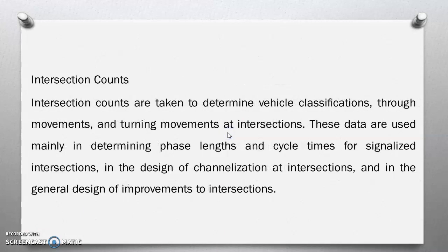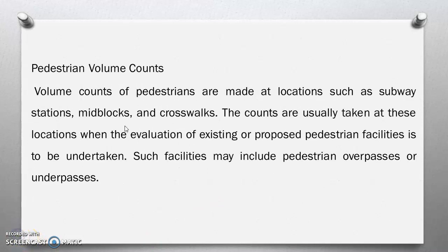Intersection counts. Intersection counts are taken to determine vehicle classifications through movements and turning movements at intersections. These data are used mainly in determining phase lengths and cycle times for signalized intersections, in the design of channelization at intersections, and in the general design of improvements to intersections.